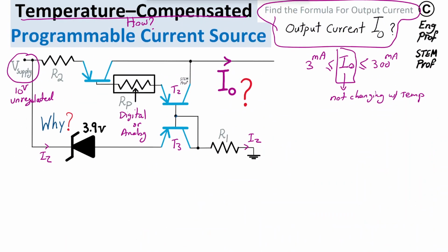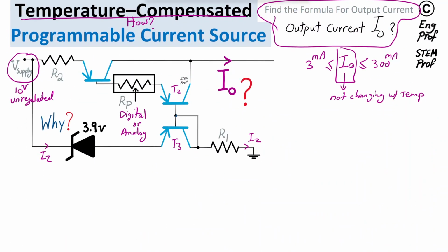So what is the meaning of that? To establish the meaning, that means the voltage drop when properly biased. Let's say we want IZ to be at least 10 milliamp to be on the safe side, so that the Zener diode is well biased. Then for that, the voltage drop across the Zener diode, VZ, has a nominal value, which is 3.9 volt.